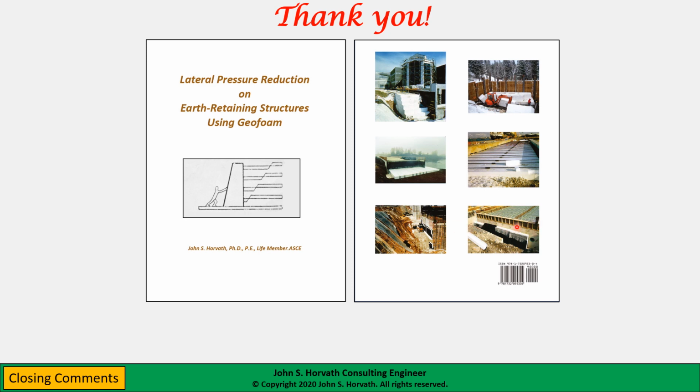And this final case history slide is for a semi-integral abutment bridge in Virginia in the United States. I did not get into semi-integral abutment bridges at all in my presentation. I mentioned them, but I did not get into them at all. They have many of the similar problems to integral abutment bridges in terms of the fact that these short stub embankments are moving with the bridge deck, in this case due to seasonal thermal changes.